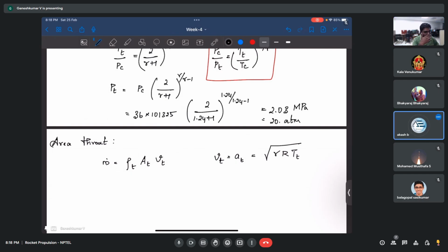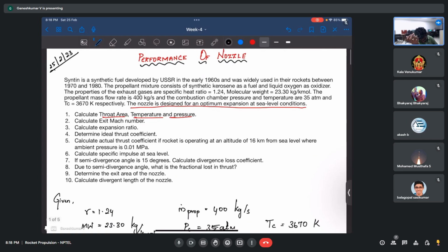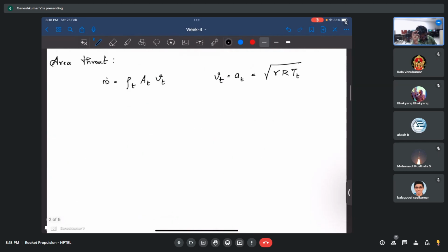I have another way. We can also write the area ratio like Vt rho t by Ve rho e, right? Arranging the equations. We don't know Ve yet, right? Ve is the jet velocity. We can find it through... Actually, that is coming next. We need to find the exit Mach number at that time. Also, you can find it; there are a lot of ways. You are telling we can find it using m dot is equal to...